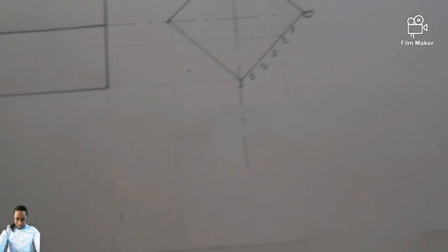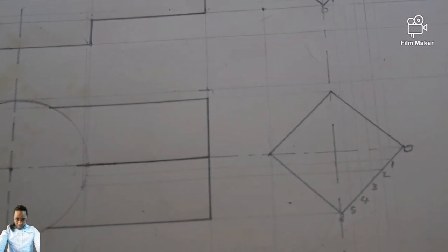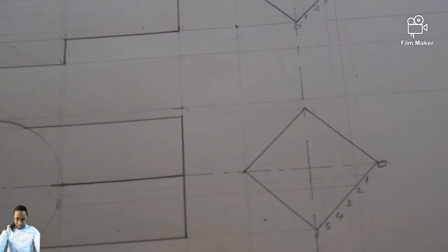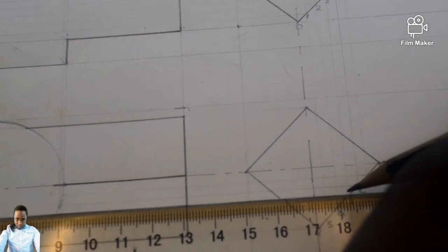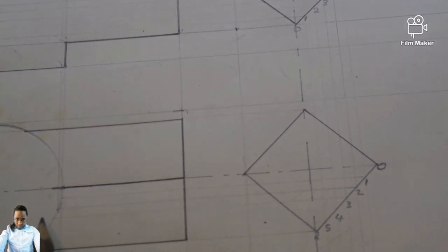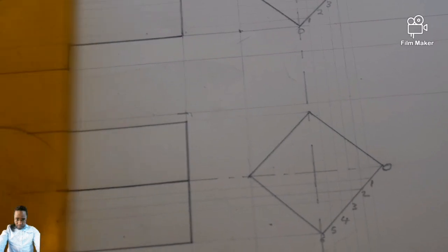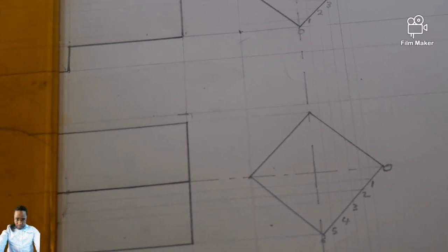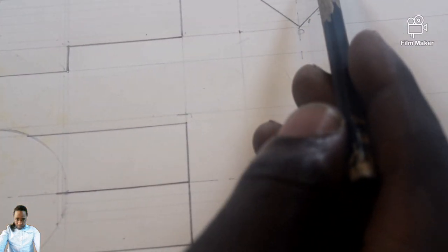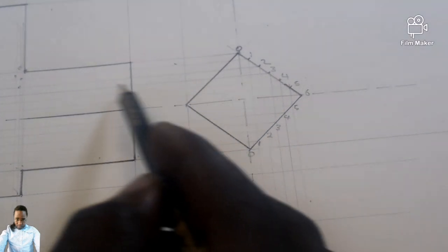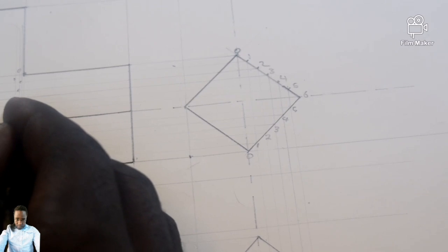Let me do it. The camera for the YouTube is giving me a tough time. And then this is 3 from the auxiliary top. There it goes. Once it touches the main pipe, faint, isn't it? Once it touches the main pipe, there it is. You project it up. Must go and intersect with the 3 that was going horizontal there by our auxiliary front view. There it is, which means I've got a point right there.